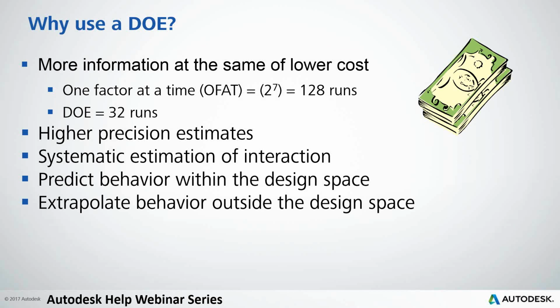A DOE analysis can be done in 32 analysis runs. It is important to note here that performing a DOE reduces the amount of jobs that you need to run to get the same amount of information, and it obtains this information in a smarter, more optimized way. A DOE is like doing parallel processing versus serial.